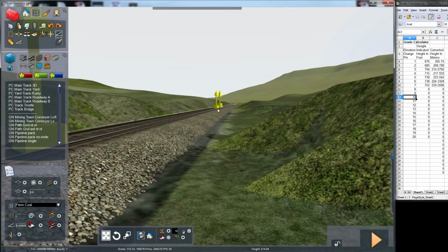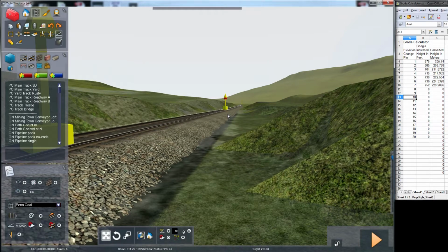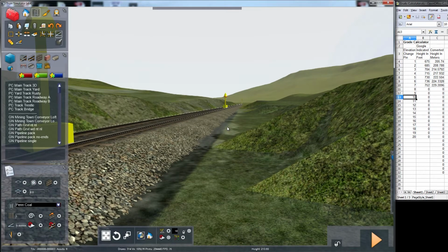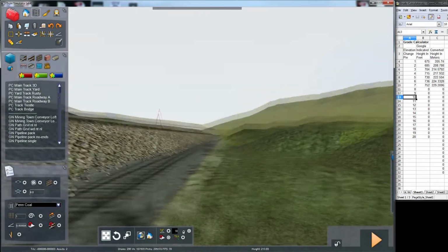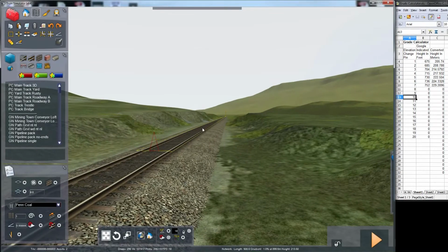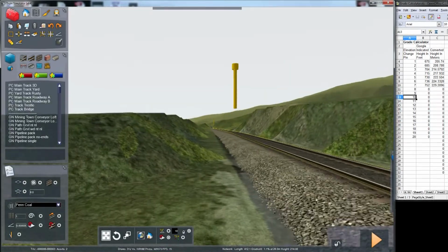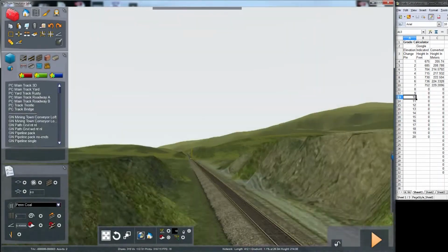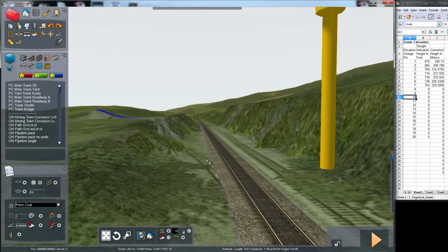Sometimes when you get a grade corrected, it will give you a little red line down between the sections that you're connecting and lowering, kind of indicating that you've gotten it to the right location. It's not going to do that this time, but I'm going to do it by eye. That looks pretty good. Don't see an elbow there. Let's see what the track looks like here. That's a 1% grade. This is a 1.1% grade. Alright, let's continue on to our next marker, which should be 715 feet, or 217.93.